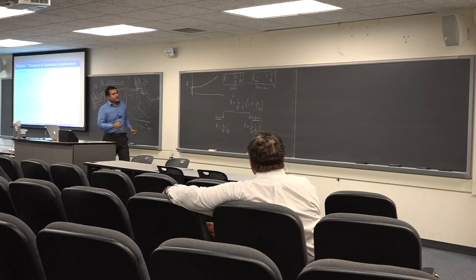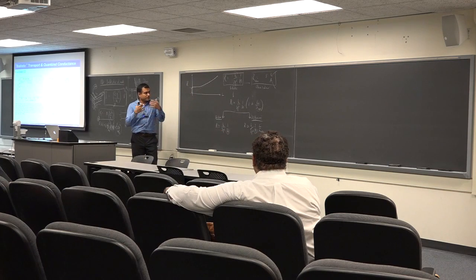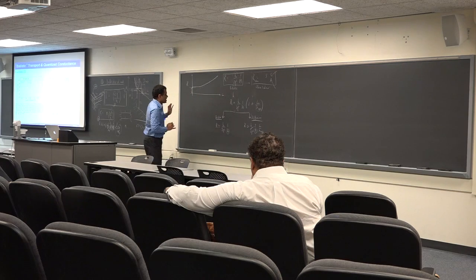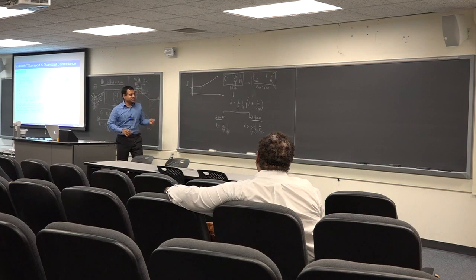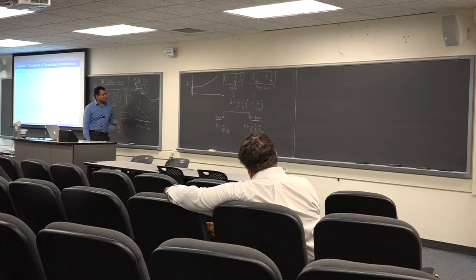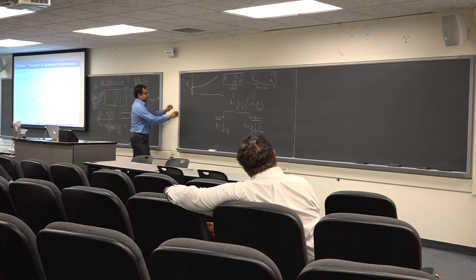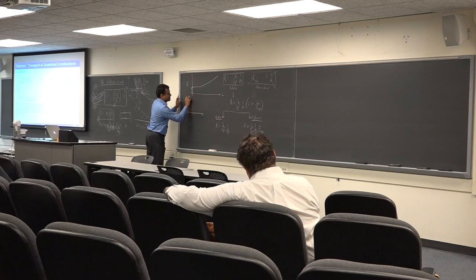So the M should increase with the number of electrons, but at the same time, the physical dimensions really play a big role. So what I'm going to do now is look at it in 2D, and then you can see why we'll make the connection to 3D as well. In a way, we have started talking about the ballistic FET now, because there it's the electron gas. So instead of 1D conductors, let's look at 2D and at what I mean by the number of modes. In 2-dimensional space, I'm going to just draw the k-space picture.